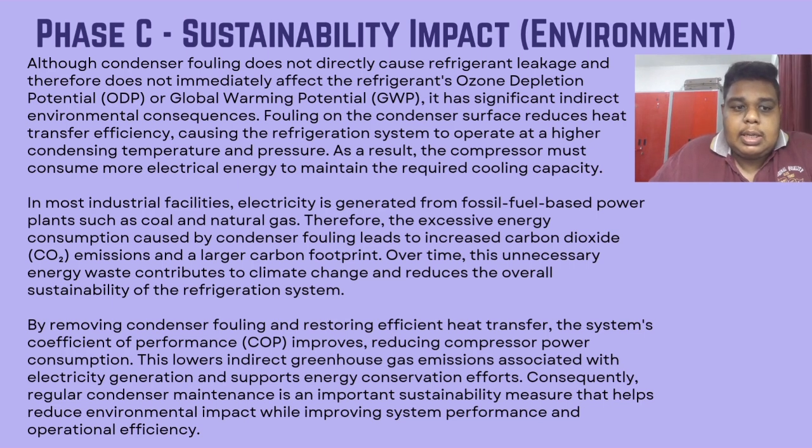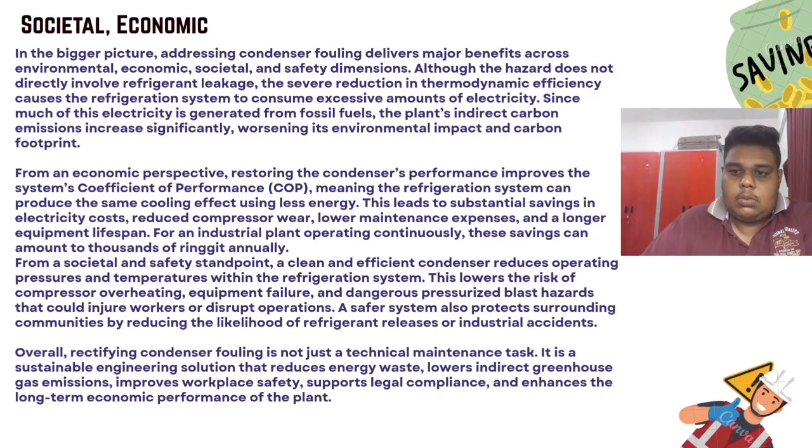Since electricity is often generated from fossil fuels, this increases carbon dioxide emissions and the system's carbon footprint. Regular cleaning and maintenance restore efficient heat transfer, improve the coefficient of performance, reduce energy consumption, and lower greenhouse gas emissions. Therefore, controlling condenser fouling is an important step towards improving energy efficiency and environmental sustainability.